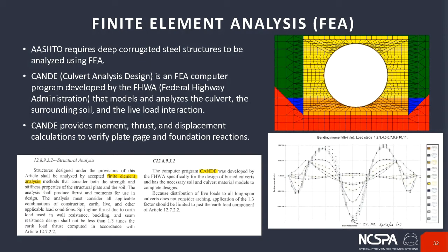The FHWA, the Federal Highway Administration, developed a finite element analysis program called CANDE, which is short for Culvert Analysis and Design. I have put a couple of screenshots on this slide. In the top right, you can see a mesh for a round pipe, and the bottom right is a bending moment graph that's output. This models and analyzes the culvert, the surrounding soil, and the live load interaction specifically for buried culverts.